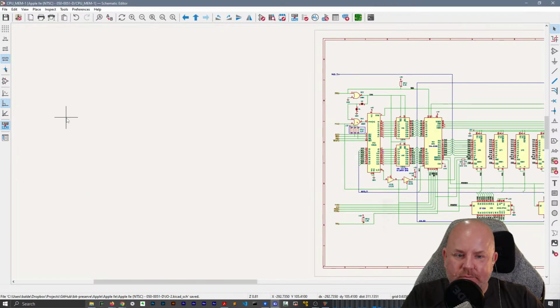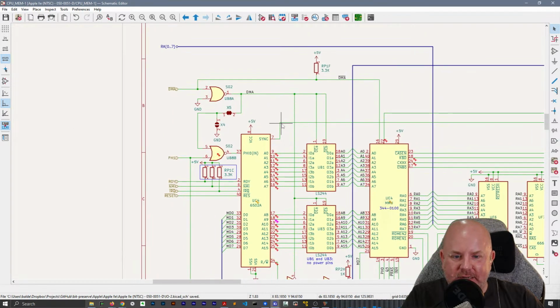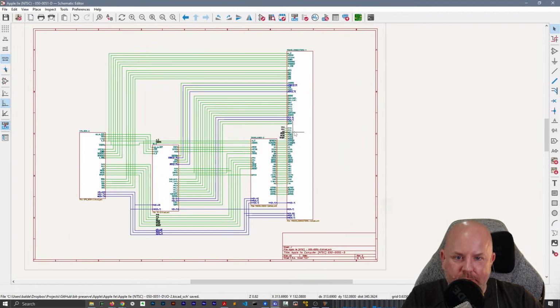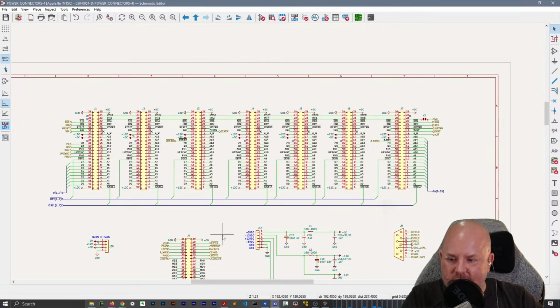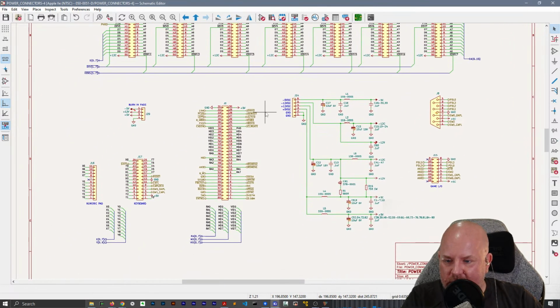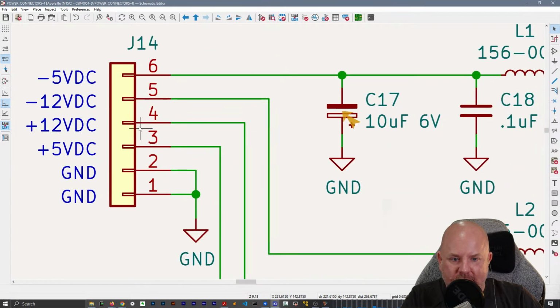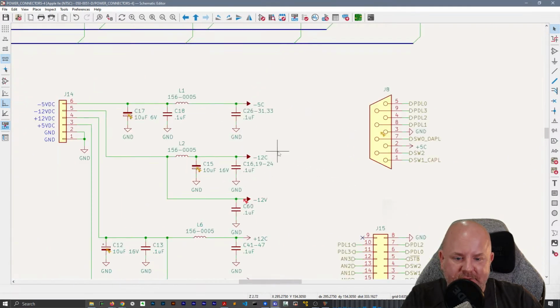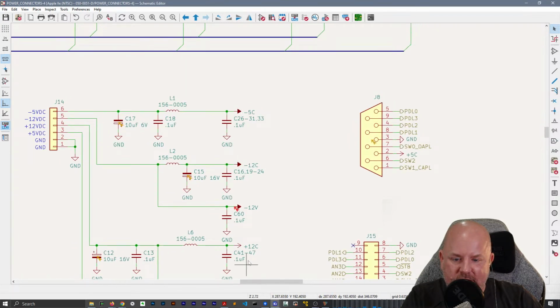Okay, so input pin not driven by any outputs. I'm going to do a video on just this error message because so many people get messed up with this. So what we've got to do is tell KiCad where does power come from? And power comes from these pins right here. Specifically these over here. So what we need to do is extend this out a little bit because we're going to add...